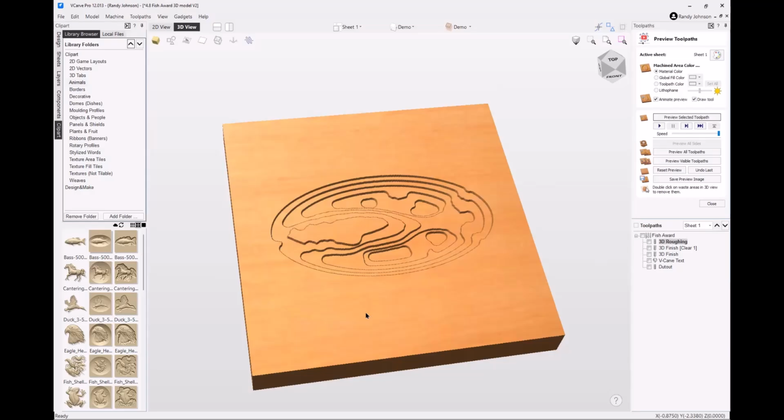I use an up spiral bit for almost all my cutting and carving when I use a 1/4 inch diameter. It's very effective because it has a shearing action. It leaves a smoother edge cut. The only drawback of an up cut is that in plywood and solid wood, it can lift the grain at the top surface. So you sometimes have to take that into consideration when you're doing your carving. Sometimes if you set that first pass real shallow, or if you go a climb cut, then you can avoid the chipping.